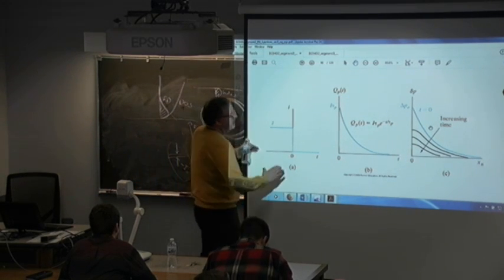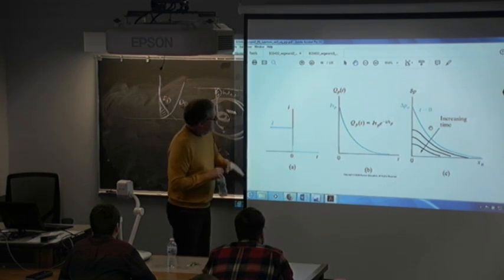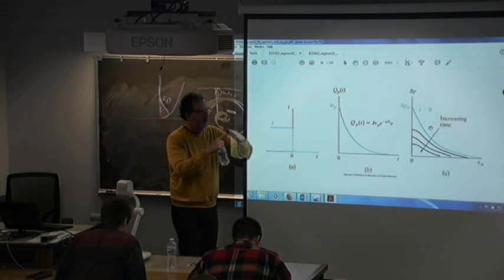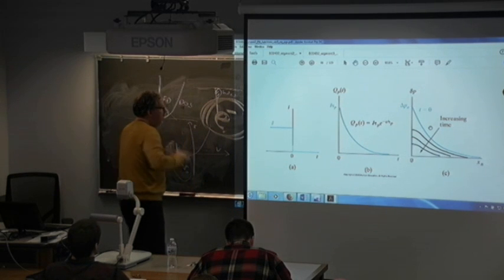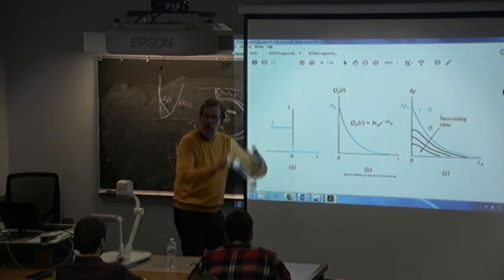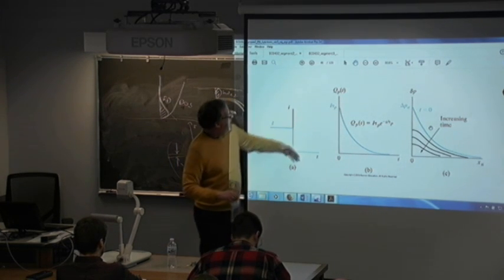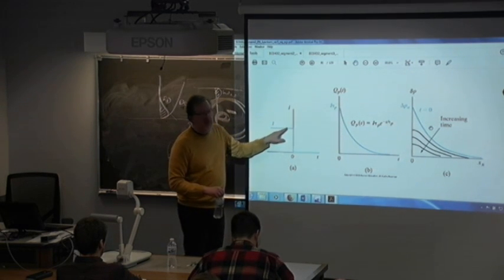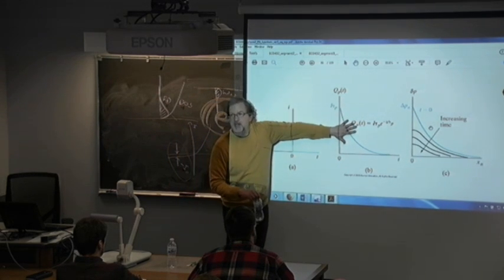So again, this is the buildup of the charge at the edge of the depletion region. So the current is high, so it's under forward bias. So we have greater than equilibrium values. Kind of have a very truncated board, so it's hard to draw. But I have accumulation on either side, so this is only showing you one side. And then I turn this diode off, so I go from 60 miles an hour to 0 to a dead stop, and they have this excess charge.